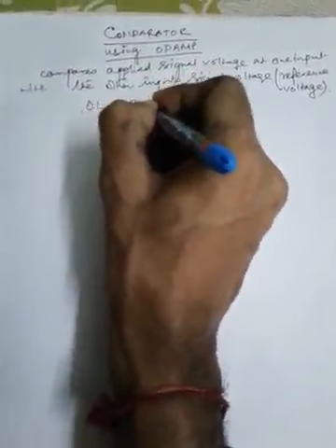Now, in the simplest form, it is nothing more than an open loop op-amp. This is basically the comparator. So this is the open loop op-amp circuit, the basic comparator, and it has two analog inputs and a digital output. The output may be in positive saturation voltage or in negative saturation voltage. That means it is a digital output, one of two stable states, and the inputs are obviously two analog signals.